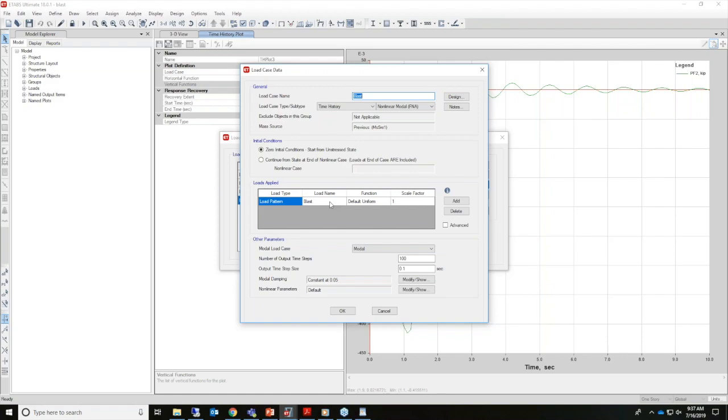Another question, can we do time history analysis in two directions in one analysis? You can, yes. You need to be careful as to viewing the output because it can get a little muddled. I prefer to do them separately, so you can take a look at the output individually. But yes, you can do a time history analysis for accelerations in different directions in the same load case.